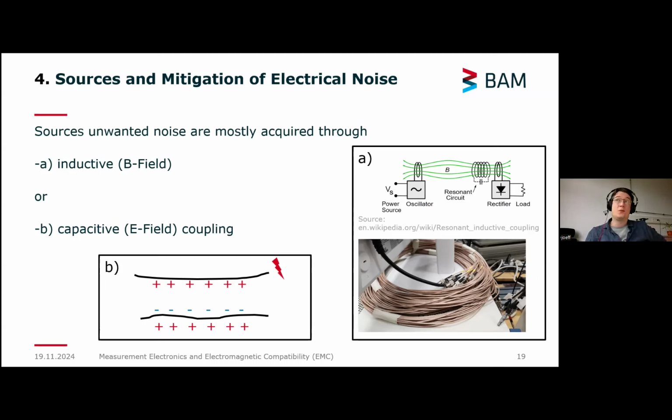You can have one signal on one line, it might jump over to the other line, and you would have a signal at a place you don't want it. Also, a side effect of high voltage lines: ultrasonic transducers might get driven by high voltages, like 150 volts, and you have pulses on them. You might have seen the pulse appearing on a different line, which would be the capacitive coupling on the bottom left.